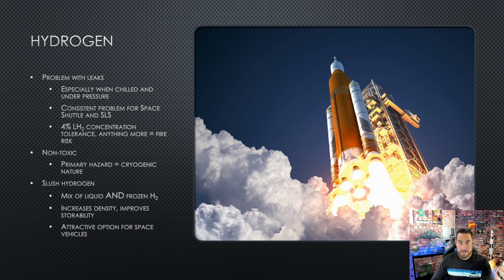Anything higher than that leads essentially to a scrub. So actually with the space shuttle, they had an average of 1 scrub per mission, which means that whenever the space shuttle was supposed to be launched on the day and time, it essentially never launched on the day and the time it was supposed to. In some missions, they had 5 scrubs before they could ever launch, and most of the time this is because of liquid hydrogen leaks. So you can't have these leaks, you can't have these high concentrations.